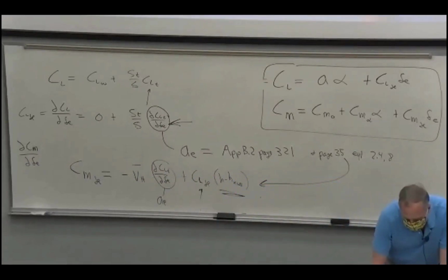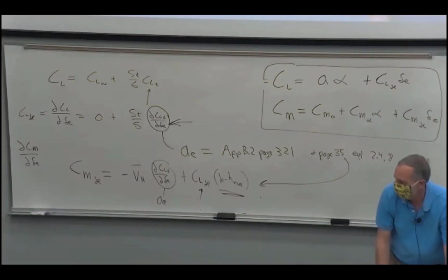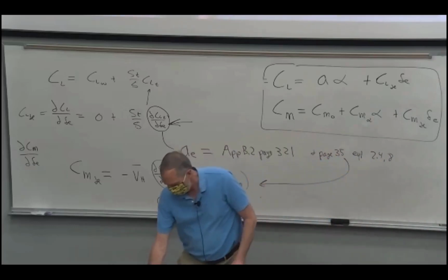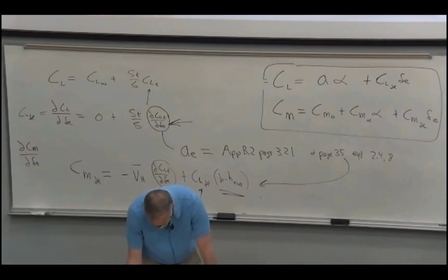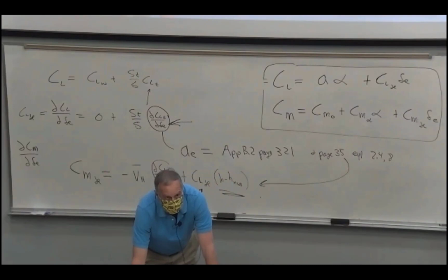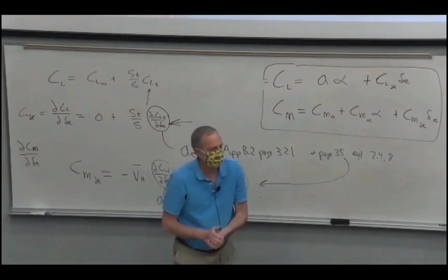Let's see, somebody has a question on here. Do we have equations provided for question 2, parts B and G? I think we went through that, didn't we? Part B, the canard lift curve slope, is the big giant formula for the lift curve slope. And what was the other one, G? Yeah, there are formulas in the lecture or in the class notes for what VC and VC bar are.